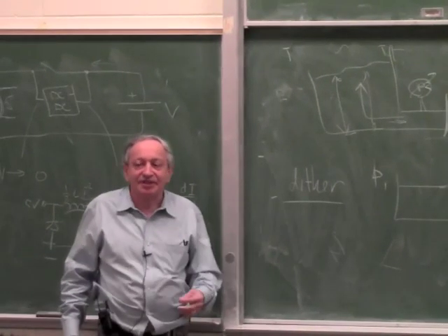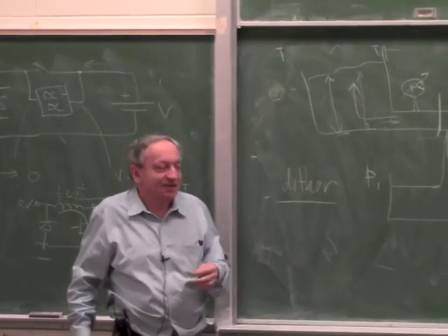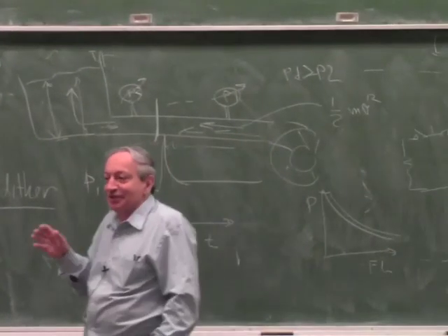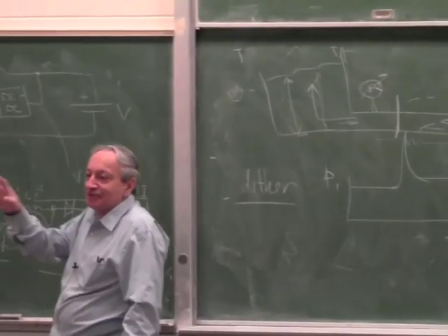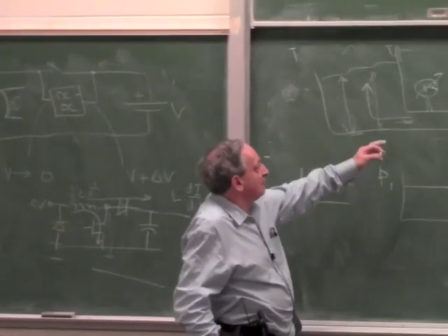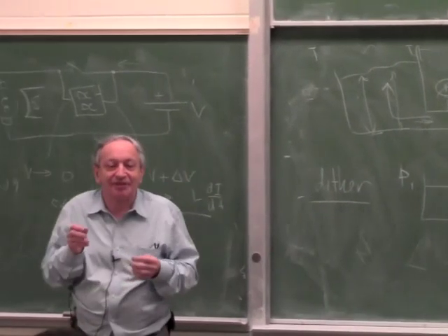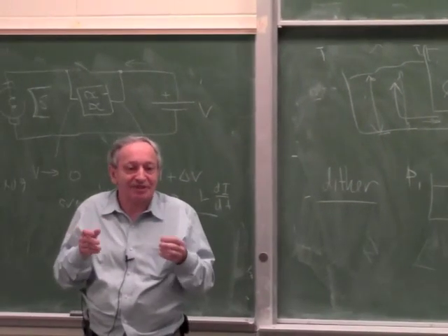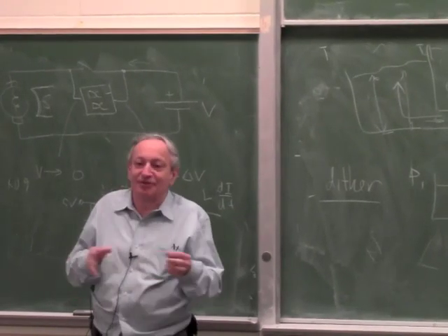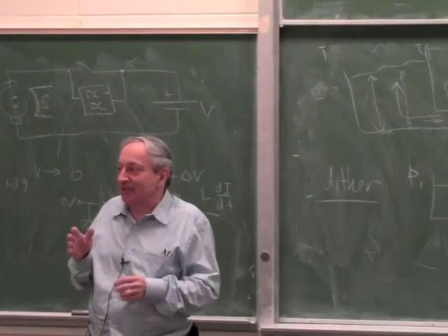See, hydraulic servos have a lot more stiction than electrical things. Because the nice thing in electrical servos, the electrons can flow very smoothly. Whenever you start the smallest current, the electrons start flowing, or smallest voltage. But in a hydraulic system, when you have valves and pistons, there is static friction. You increase the pressure a little bit, it doesn't move. Just like stiction in mechanical systems. Right? You have to overcome static friction before things start moving, and that causes some backlash in a servo. A bit like hysteresis, right?